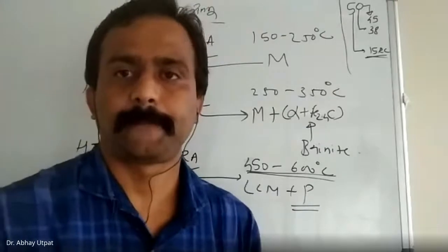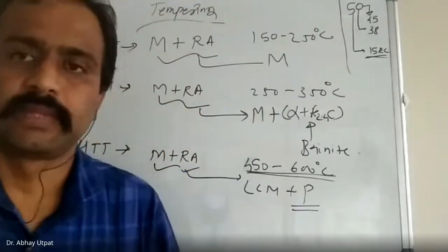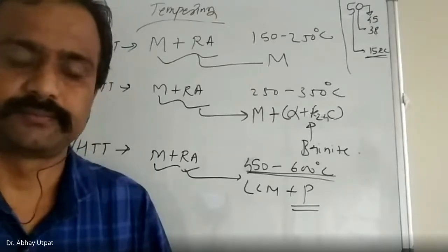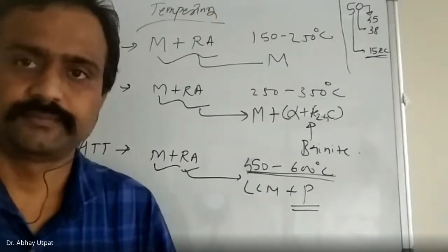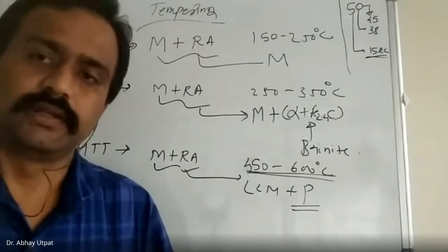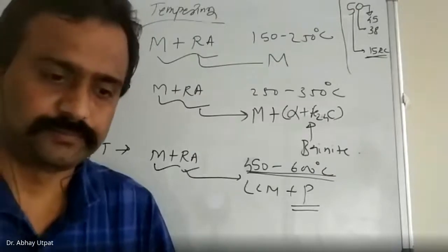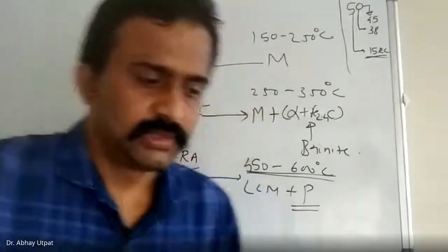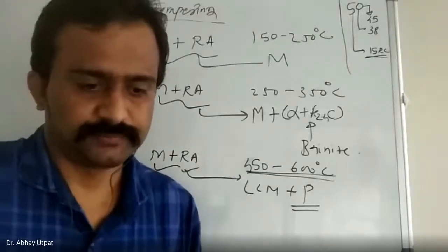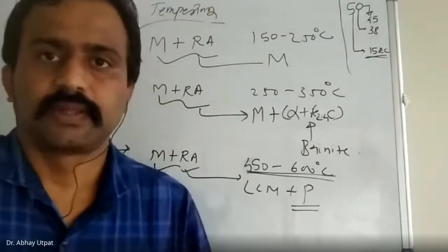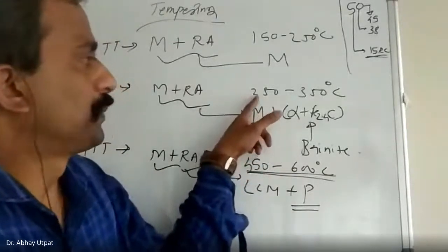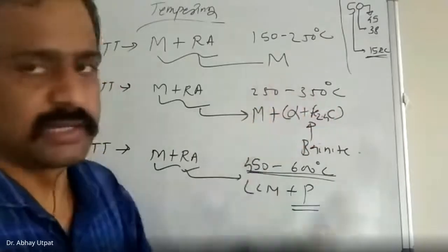Second, medium temperature tempering. Underline it. It consists of heating the samples to 250 to 350 degrees Celsius.